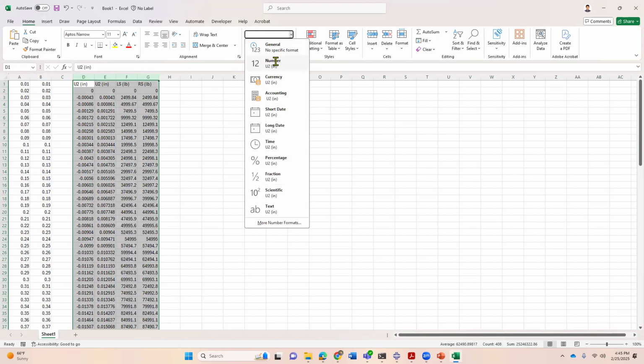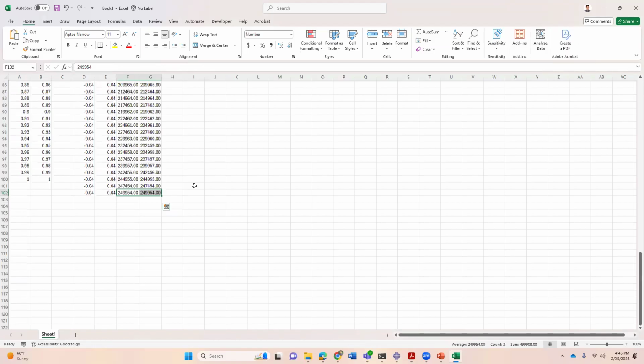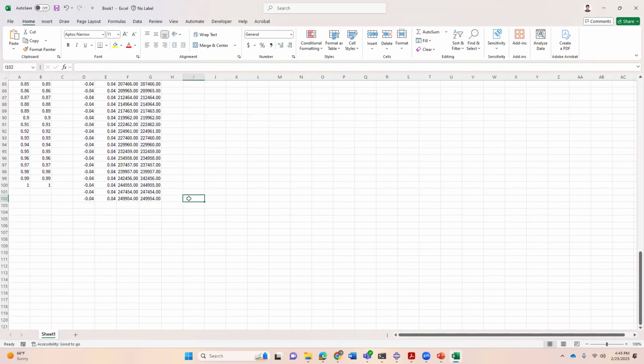So now we can have, say, the total force. So the total force we applied is 50 kip per feet. So 50 times 10, my beam is 10 feet length, right? So the total force is 500 kip. Let's add these reaction forces at the very end, and it should give us the total force, okay? So if I add this plus this, both should give us 500 kip load. So that means 500,000 pound. As you can see, it's 499,999.08 pound. That means it's 500 kip.